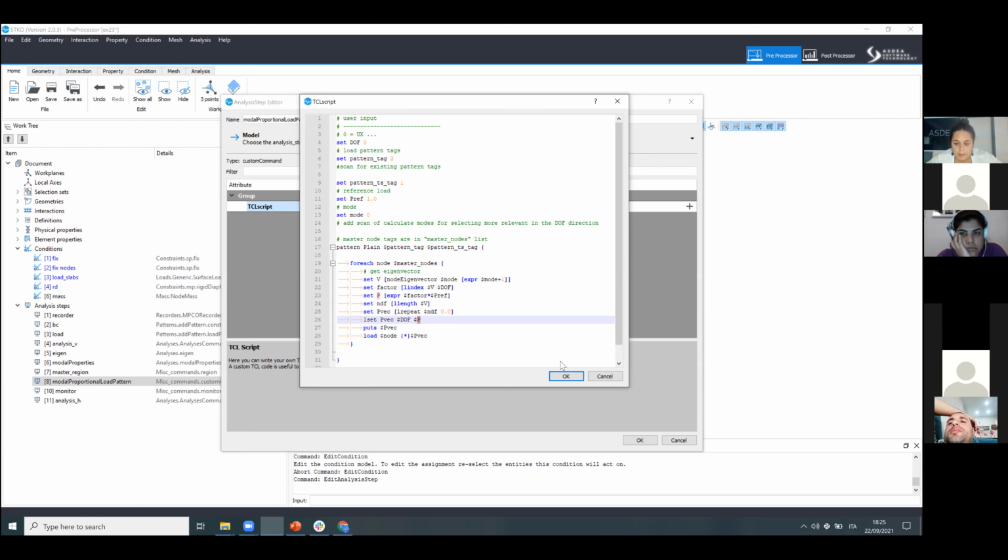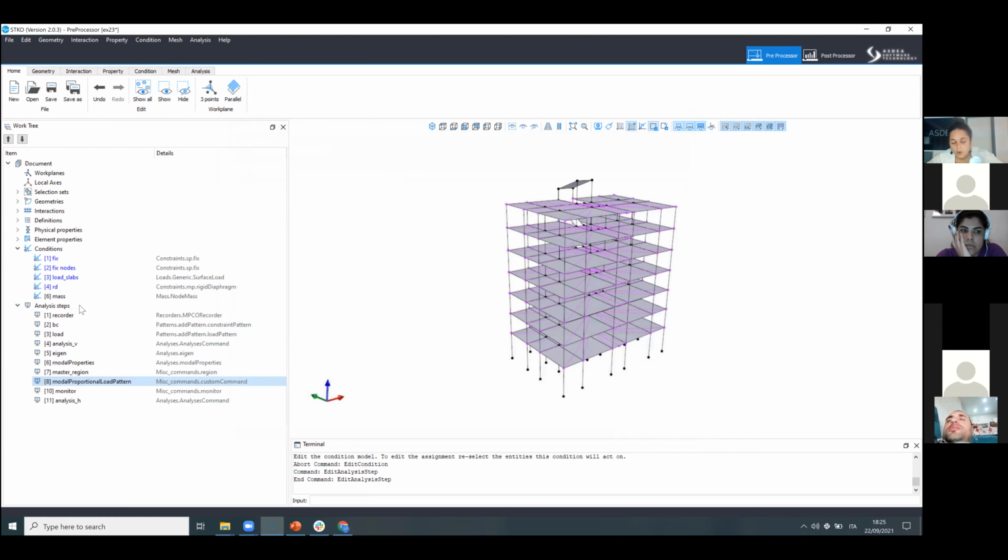This is just the same as going here and creating a node force. I don't have the run analysis now, but anyway, if you open the MCO file in HDF5 viewer, you can see the eigenvectors for each of the nodes that you want. And this is the same as going there, taking the value, putting it here, adding a node force, selecting the node and doing that. So this script does exactly the same thing.